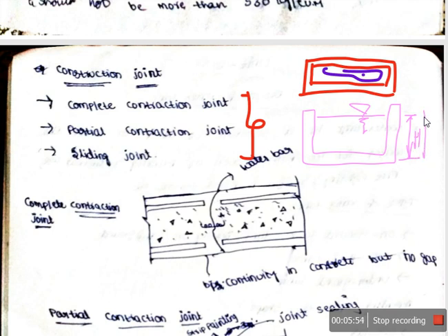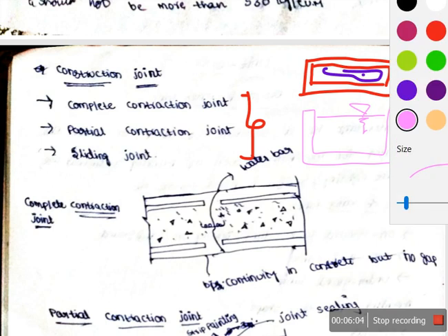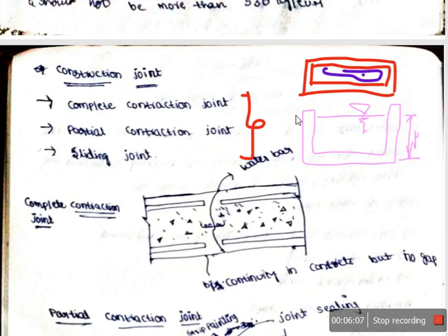And you have the same kind of force which we have done in the retaining wall design, but there the soil is there, and here we have water. Even water has the same kind of pressure variation. Here it is wH, and the total pressure you can calculate as half wH squared.